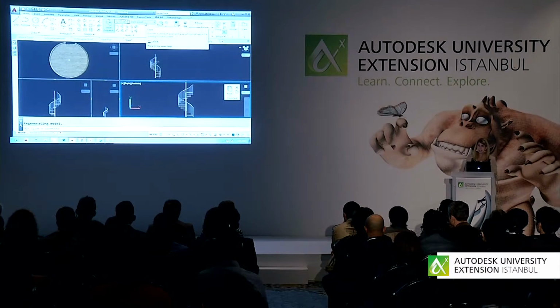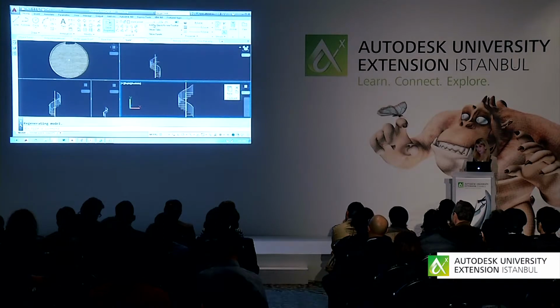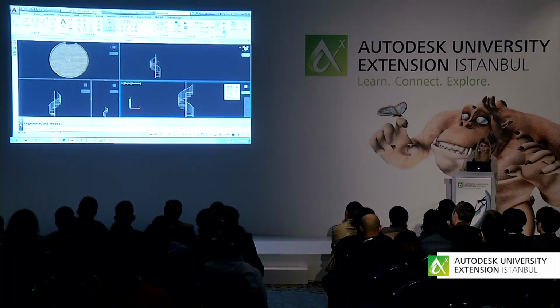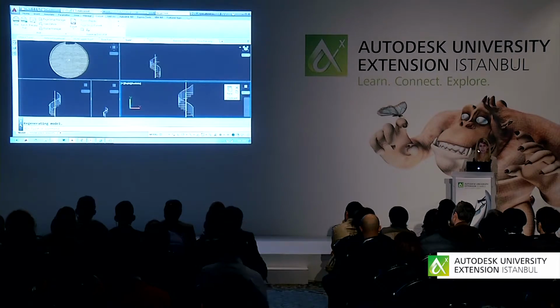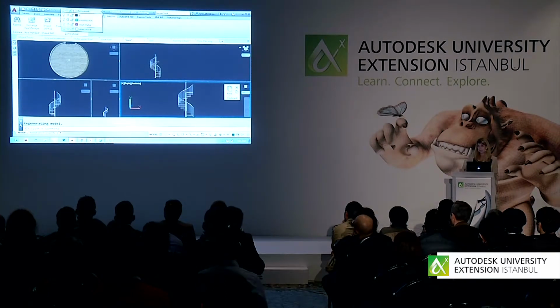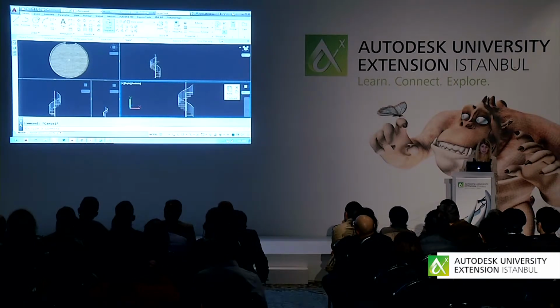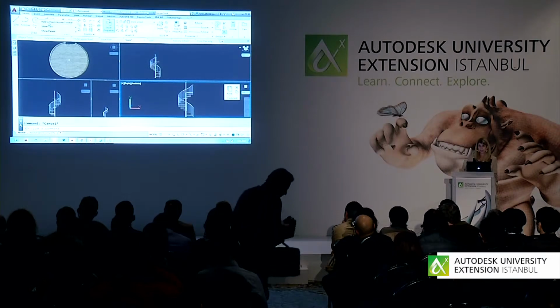So you can actually take any tool, for example, the layer drop-down list, and you can right-click on it, and you can say Add to the Quick Access toolbar. And you can see now that I can very easily change layers without having to go to the Home tab in the ribbon. I can go to any tab, and I can always very quickly change layers. So you can do a right-click on anything in the ribbon, and you can add it to the Quick Access toolbar.